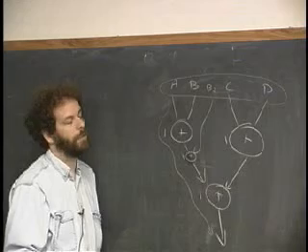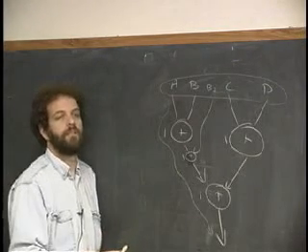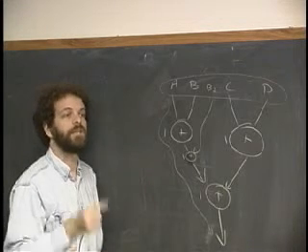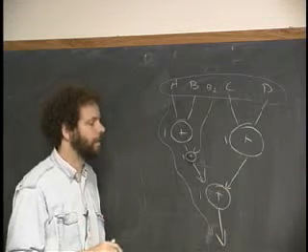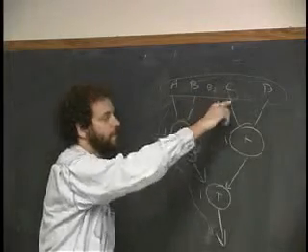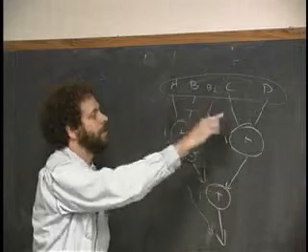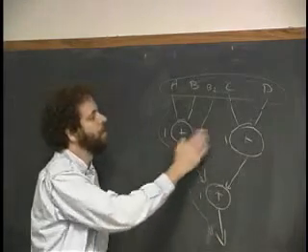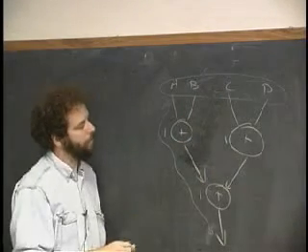Let me ask a real quick question. If the contamination delay of each of these things was 1, what would the contamination delay of this circuit be? 2. Good, because it's the minimum of the contamination times. Because once you put trash on here, it's the fastest the trash can get through, which is this path here. Once you put good data on there, it's the slowest it takes to get there, which in this case is 1.